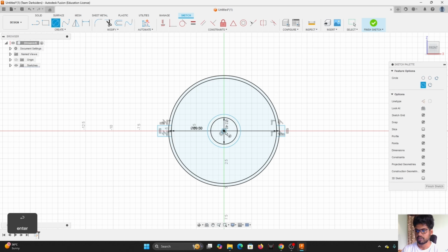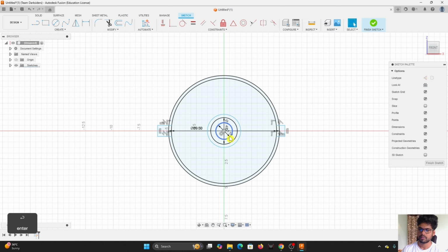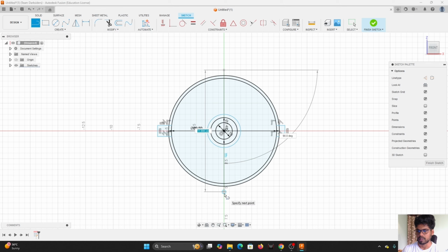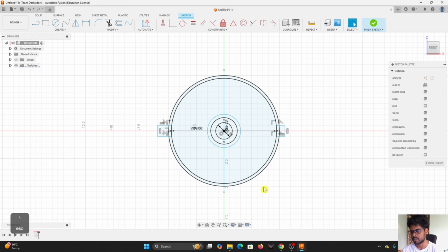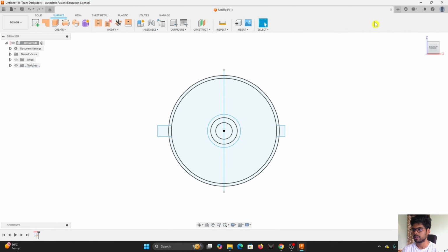Also, there's another button. So this will be the light up button that goes red and green. Also, we need another button that is used to push to enlarge the Pokeball. Let's make this about 1.5. That seems about right. Also, before we finish the sketch, we need an axis to revolve our paths along. So let's just create a line. This will act as an axis for us to rotate these parts around. And yeah, that's it. We're good. Let's finish the sketch and we're done with the sketch.